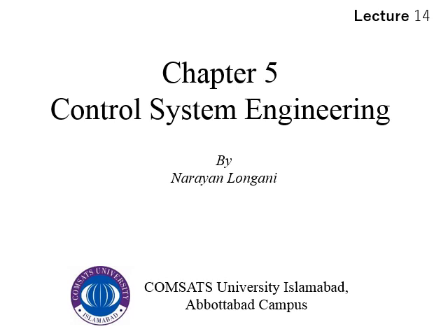Then we studied various topologies for reducing a complicated system to a single block. These topologies include cascade form, parallel form, and feedback form. If any arrangement of subsystem is not in any of these forms, then we use moving of block across pickoff point and summing junction to make the desired form, and then we reduce the system to single block form.